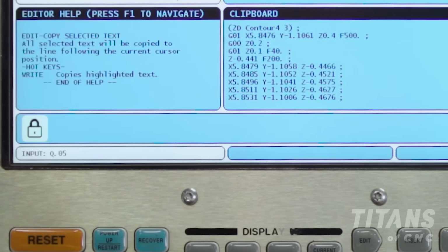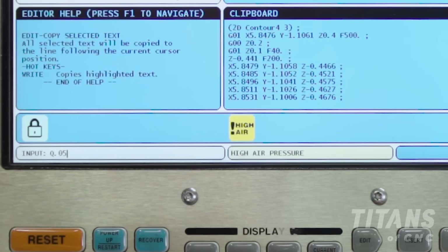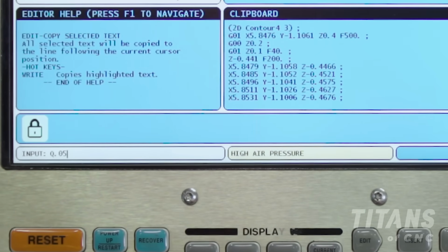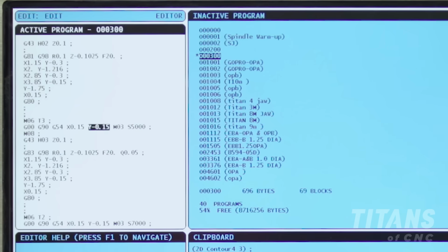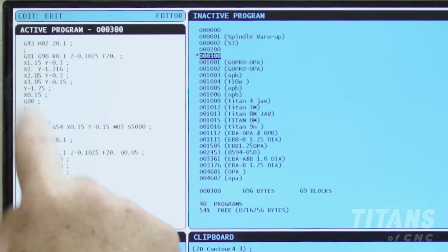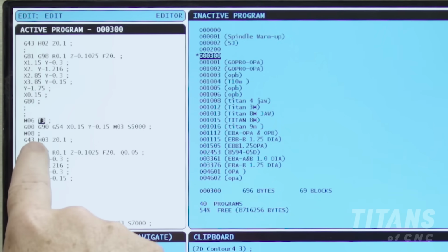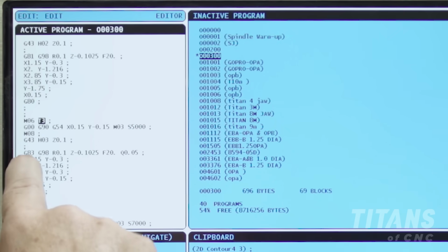So we're gonna do a Q of .050, just for safety. This Kennametal drill can kill it. I just wanna be safe, all right? And we're just gonna insert this guy. Now, T3, H3, always double checking.